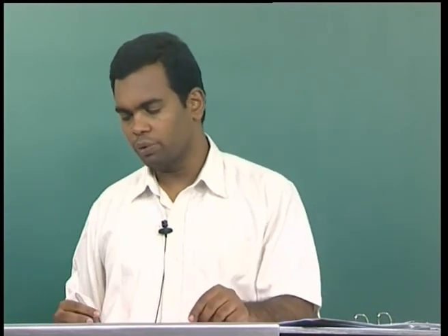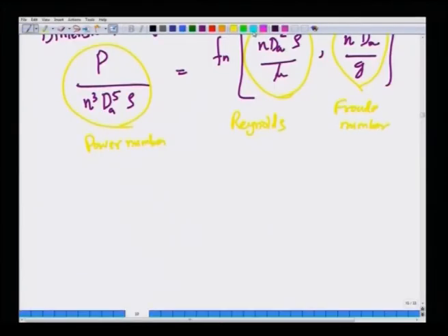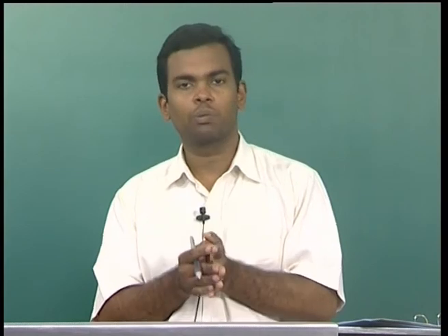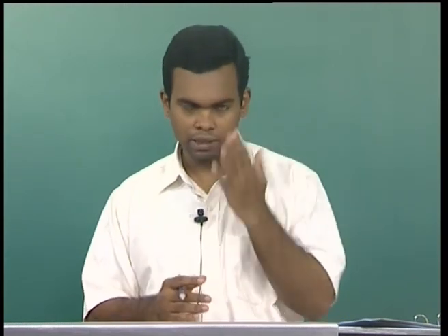So, by doing dimensional analysis, we found this, but in reality, there could be other shape geometrical non-dimensional ratios. For example, what is the distance between, this is not all, because you have to worry about all the other geometrical similarities, the distance is here, and the distance between the free surface and the impeller. All these non-dimensional ratios must be the same if you want to be able to scale up across sizes, from lab scale to the prototype. So, there are other shape factors or geometrical factors which must be included in the correlation.